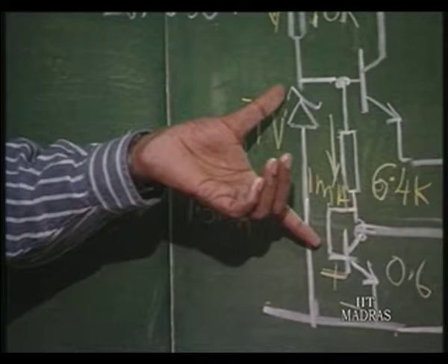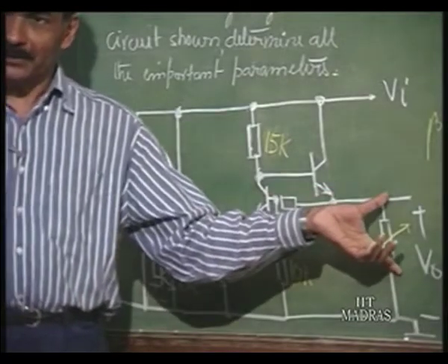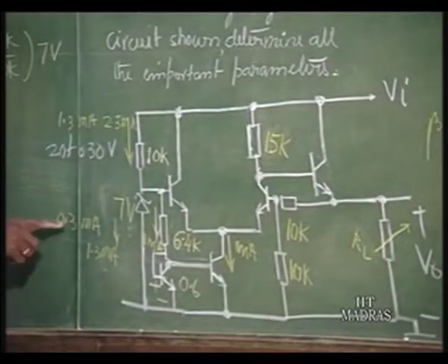That change in Zener voltage is what is going to appear at the output as 2 times that. So, let us say at 0.3 milliamperes it is 7 volts, and at 1.3 milliamperes it is 7.1 volts, higher. Then correspondingly output will be changing from 14 to 14.2 volts.